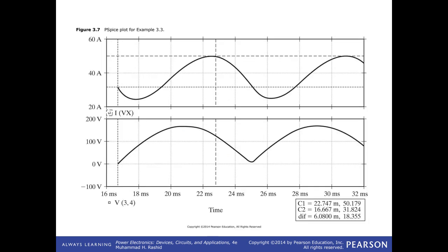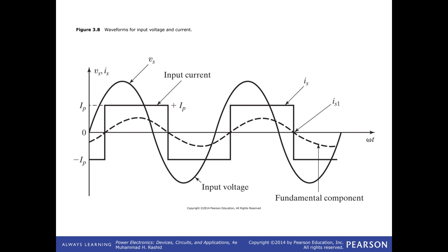So that is a kind of misleading figure, so be careful. This is sinusoidal. Follow my cursor, please. This is a sinusoidal supply, and that one is assumed to be flat DC current. Therefore, this is the reflection of the flat DC current from the primary side, the transformer input, or to the rectifier.